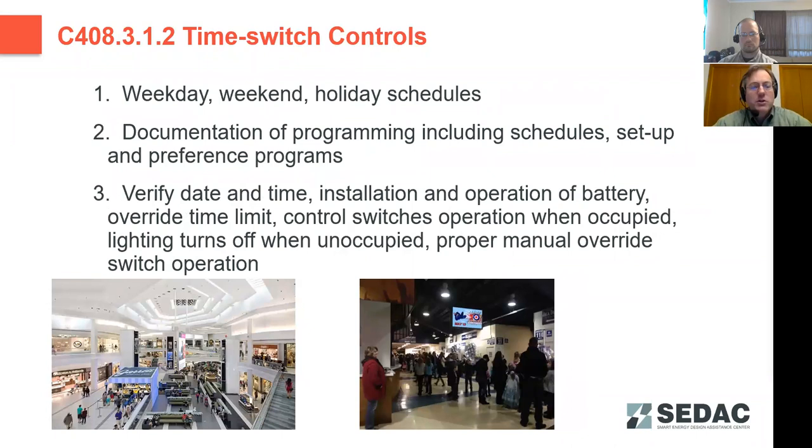The time switch controls are a little simpler. Verifying schedules are programmed, and that there is documentation of the startup schedule, because while the time switch does have to be able to maintain its program for at least 10 hours, we all understand that there are power disruptions that may extend beyond 10 hours.